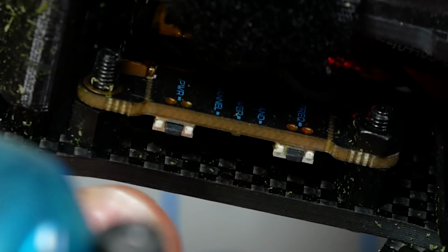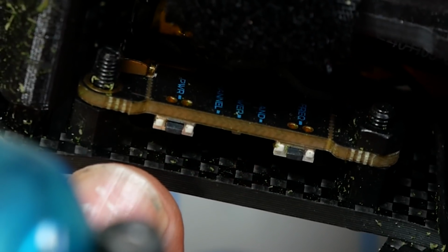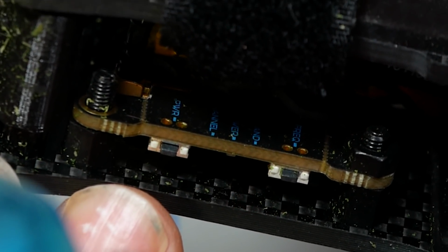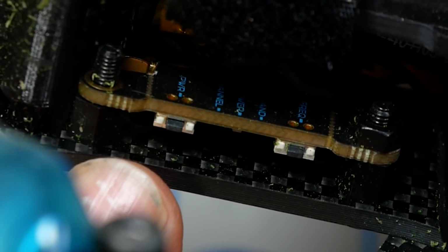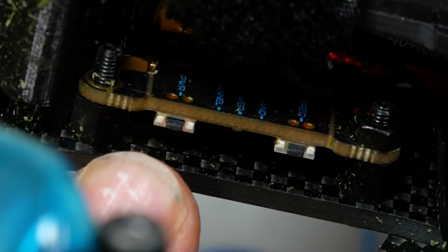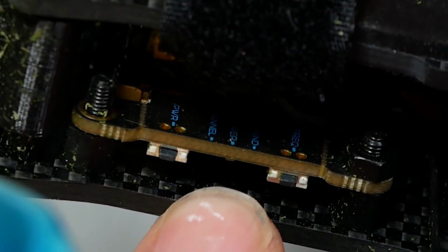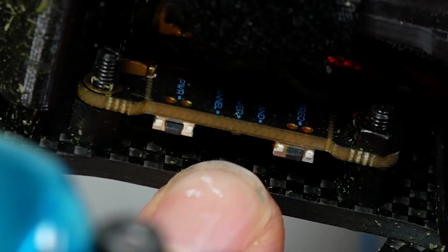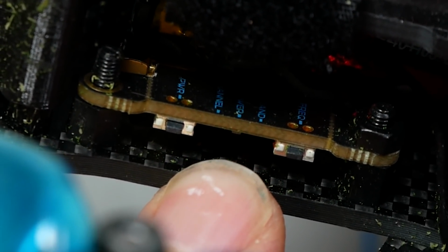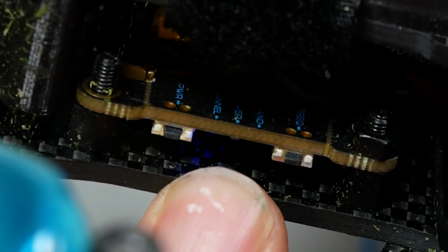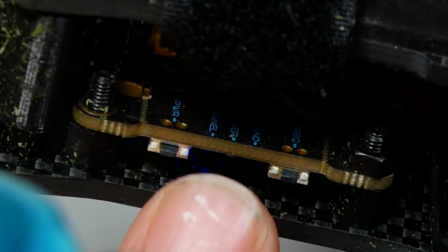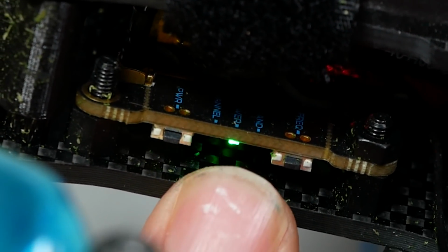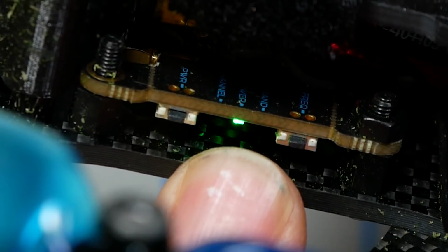Now you may have noticed that my video in that last example looked pretty bad. It had a whole bunch of static. It didn't look clear at all. And I want to make sure you know the reason for that in case you run into the same situation. So here's my video transmitter. And this LED that you see blinking here indicates the power level that the video transmitter is at: 25 milliwatts, 200, 400, 600, whatever. It changes color to indicate the power level. And what I want you to notice here is that it is blinking.